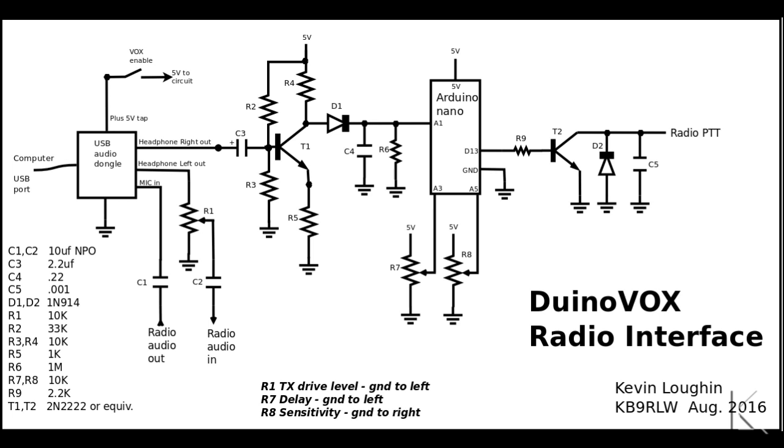It goes in the opposite direction because sensitivity is raising a threshold for the push-to-talk to a higher level to decrease the sensitivity. So you want turning it to the left for low sensitivity to increase that voltage, and then the software will increase that threshold. So wire sensitivity counterclockwise for 5 volts, wire delay clockwise for 5 volts, and the sensitivities will work right.